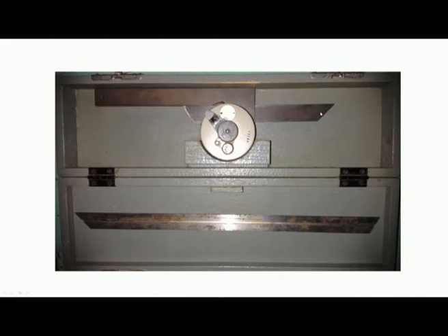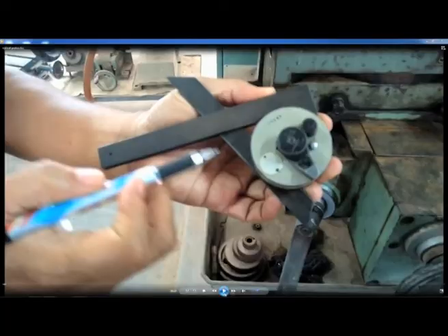Now, we will conduct an experiment to show how to use optical protractor. Now, you can see this is the milling machine table. I am trying to measure the inclination. So, this is the guideway, we have the top surface of the guideway and then we have an inclined surface of the guideway. I am trying to measure the inclination between these two surfaces using this optical bevel protractor.